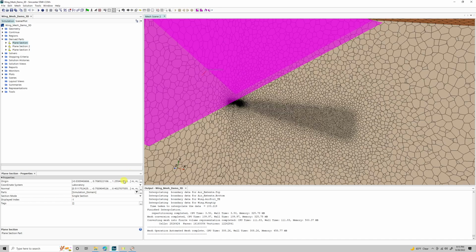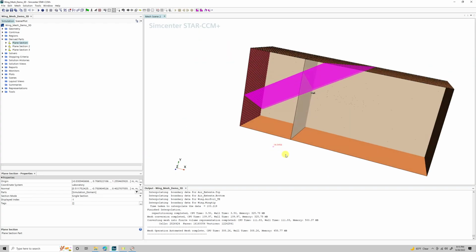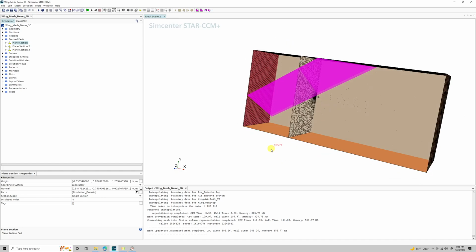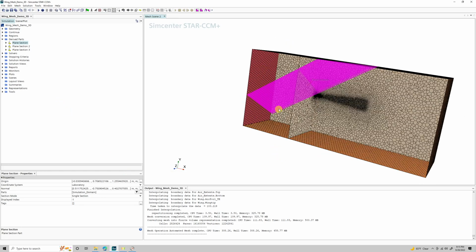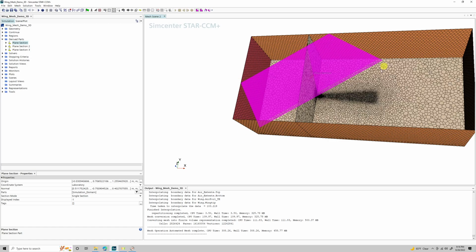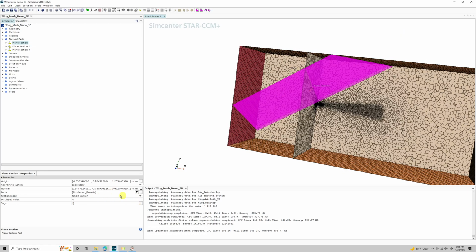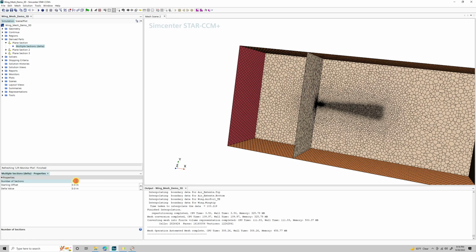Where this plane, numerically, intersects with what we are simulating, the air around this airfoil. You can see I clicked on this part and it's highlighted a kind of wackily oriented plane, but it only exists inside of this block that is our air. This is just one plane, but there are modes where you can have multiples. You can have, let's say, two sections, and you can have them 10 centimeters apart.